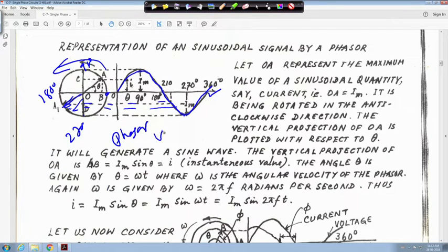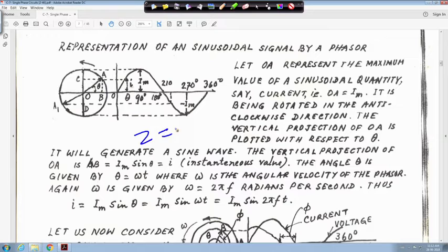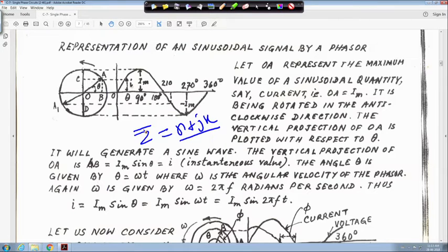That means when we write voltage this way, suppose V arrow, I arrow, this is actually a phasor quantity, right. But impedance, when you write Z is equal to, later we will see, R plus jX, right. So impedance, as you put Z bar, is not a phasor quantity. We will come to why it is not a phasor quantity, but voltage and current are phasor quantities, and a phasor is a rotating vector, right.